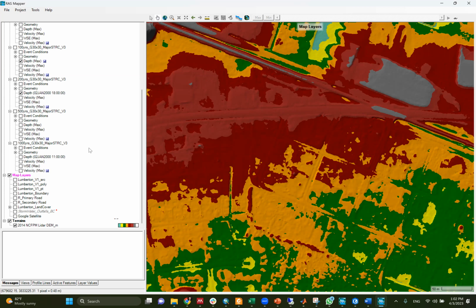but this is how I wanted to show you how the building will look like. But let me also tell you, let's assume that we have a building that has a size of 10 meters by 10 meters. If your mesh size is more than 10 meters by 10 meters, your model will not feel the building. You need a fine mesh that can feel the corner, that there is a change. For example, when you develop the mesh in the geometry and your mesh is something like this, it doesn't feel that there's a building here, because the calculation only happens at the corner of the mesh and everything here is average.